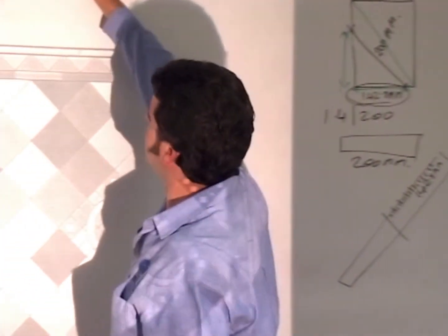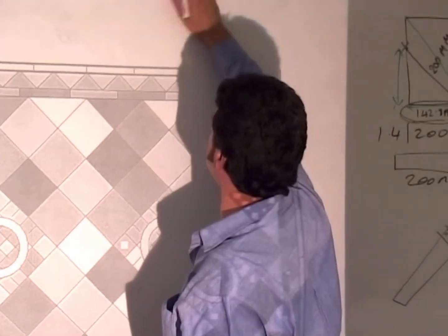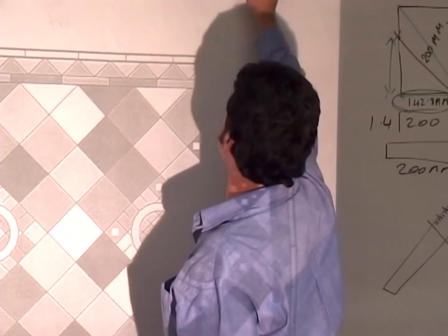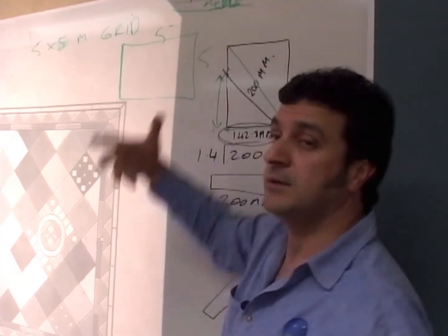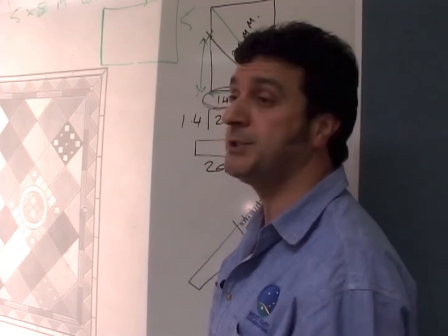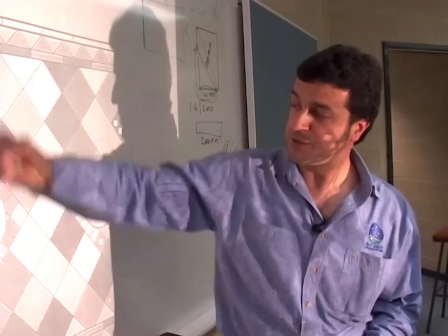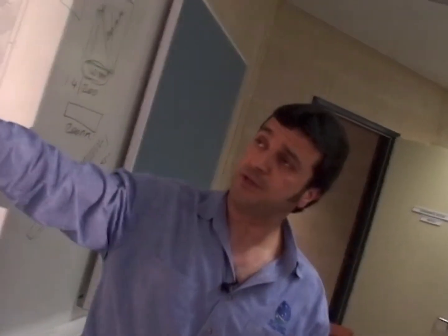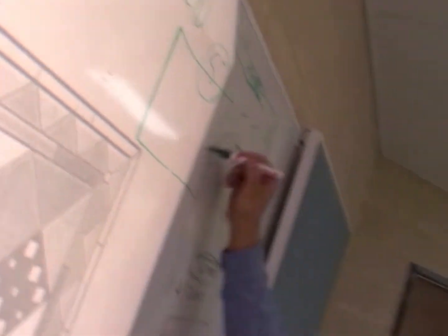But generally speaking, we're really talking about a 5 by 5 metre grid. All it has is that relief area. As tiles expand, the stresses can be relieved into the flexible filler material. And where on that floor would you lay the expansion joint? Generally speaking, you'd like it not to coincide with your inlay, because this actual span, as we said before, is about 7.345 or thereabouts. We're just going to put one which will break it down below that barrier of 5 by 5 lineal metres of floor space. Does that make sense? Yep.